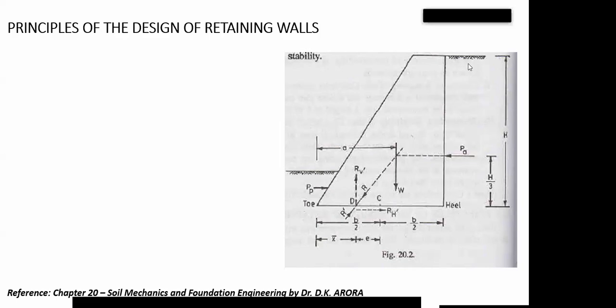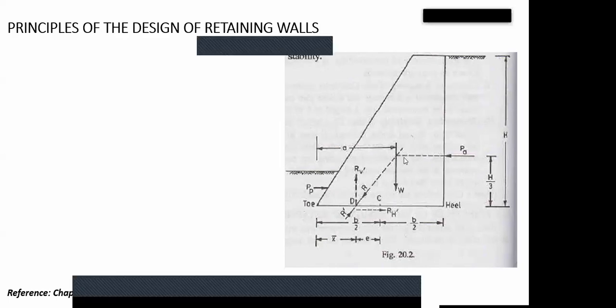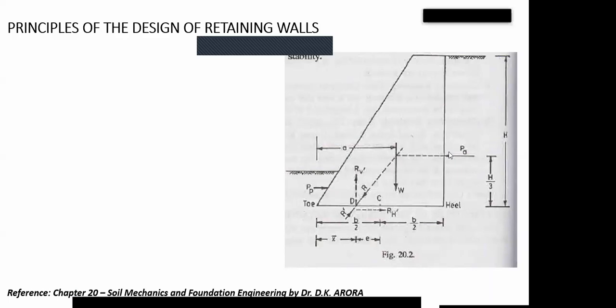Now, this back view that is acting on this retaining wall is going to be acting here. And don't forget that this retaining wall itself also has its own weight, acting vertically downward. I think I mentioned in the class that based on our experience, the line of action of a force is continuous to infinity, so I can extend it as much as I want. So I'm extending this lateral earth pressure, which is horizontal. Don't forget your lateral pressure is horizontal pressure. Now I'm extending it to meet the vertical weight of the retaining wall itself.